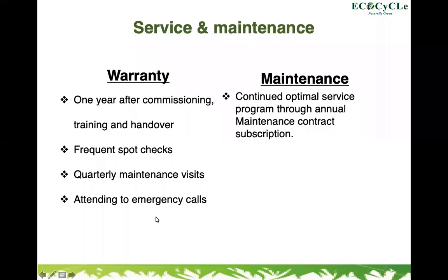Next slide. Once we install our system, we usually commission it. We first do a test run to ensure that every component is working. When I talk of every component, I talk of every process that we have talked about: the filling process, where we take the sewage from the buffer to the treatment chamber, the clear water discharge process, and the aeration process.